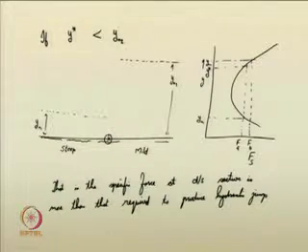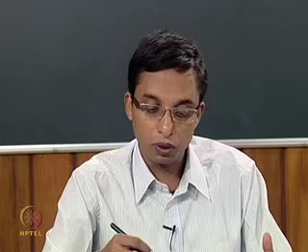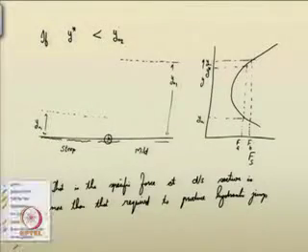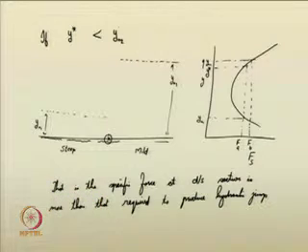So, how will the flow balance then? Here the specific force is more, you can see. I can just give it in a different ink here. You can see this portion has a more specific force compared to the downstream section, where F A is the specific force.